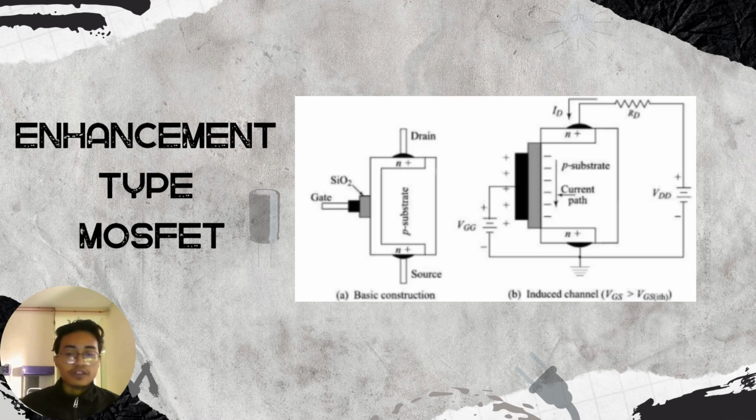Advantages of enhancement types: low power consumption when in off state, and also high input impedance leading to minimal current draw at the gate. It is suitable for fast switching and high frequency applications.